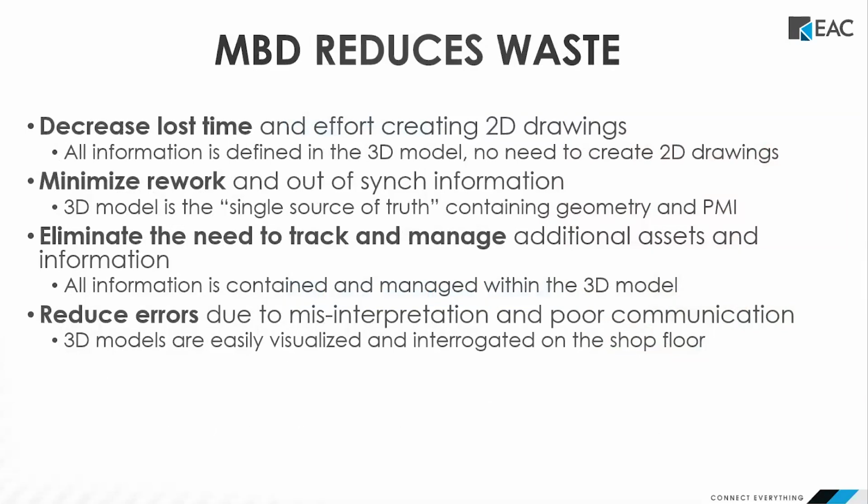MBD reduces waste. It decreases lost time and effort by not having to create a 2D drawing. Typically, it's been the rule of thumb, as long as I've known it, that you spend about 40% of your time creating a 2D drawing, aside from creating the geometry itself. You can minimize rework and reduce any out-of-sync data, and there is no real need to track any additional assets. In addition, it reduces errors due to misinterpretation, and 3D models are a lot easier to understand visually and easier to interrogate.